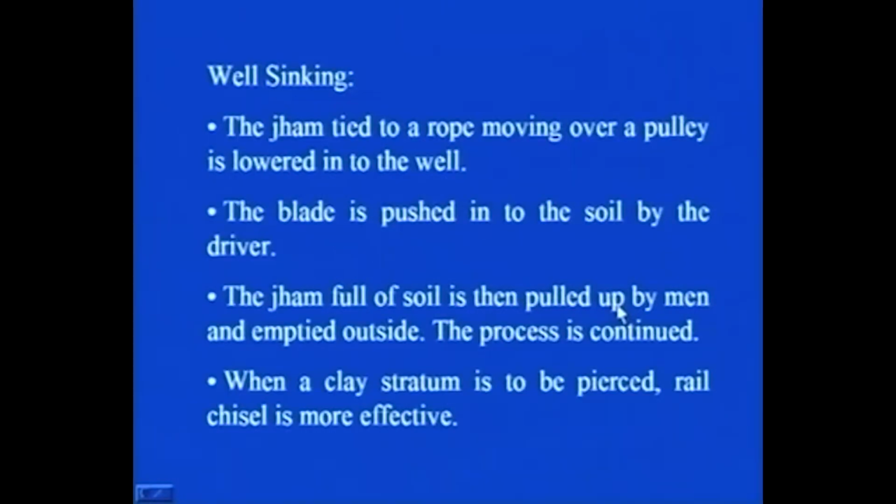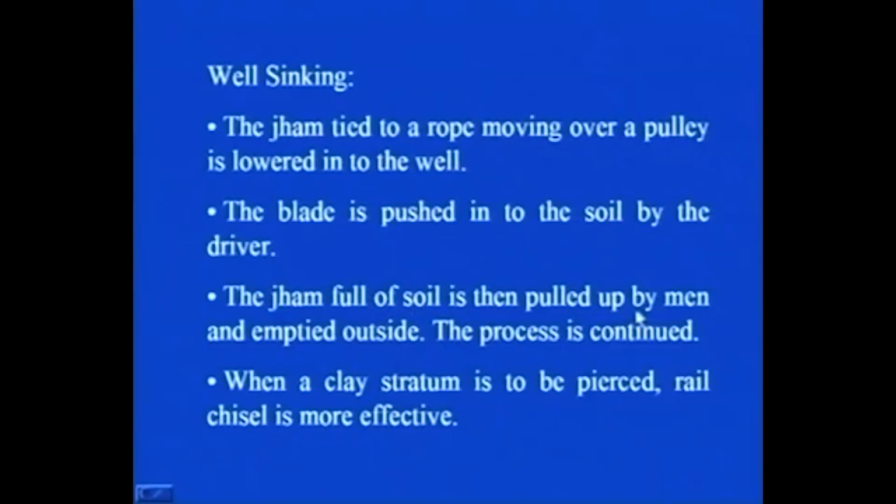How it works, let us try to see in this particular slide: the jam tied to a rope moving over a pulley is lowered into the well. The blade of the jam is pushed into the soil by the driver. Then the jam gets full of soil and is taken out. The jam which is full of soil is pulled out by men and emptied outside. Likewise, the process is continued till the total excavation has taken place.